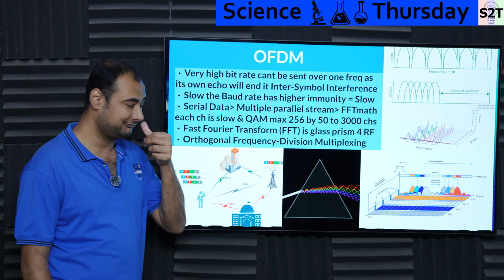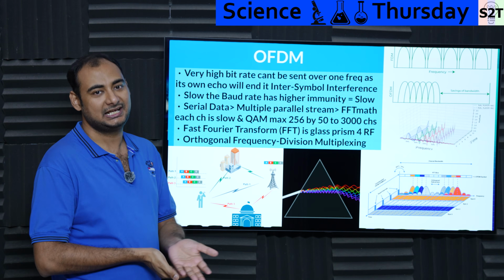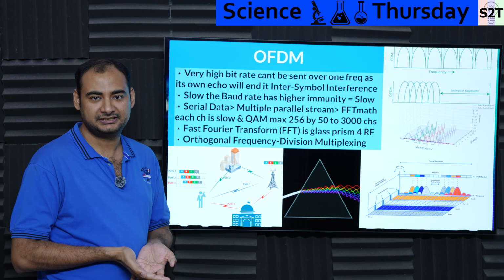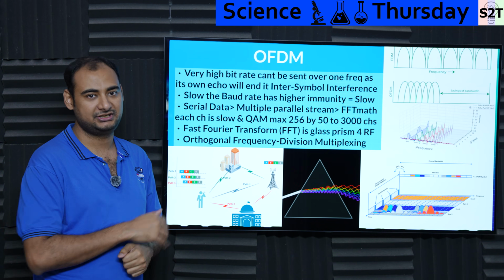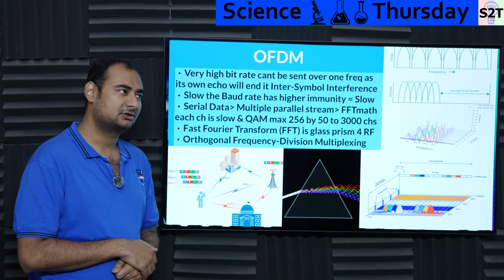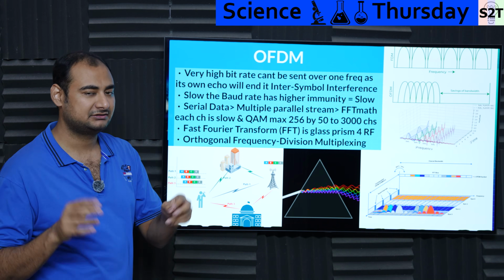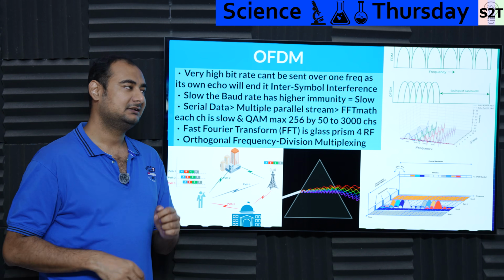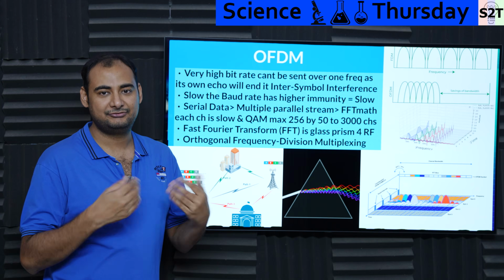Then we come to OFDM. Now OFDM is like a counter to reality, as in reality says, oh, you want to send so much frequency, we can't send it, right? Because again, signal degrades too quickly, noise overlaps everything, we have to reduce the symbol map. And then like, okay, what if I increase the frequency, increase the baud rate? Whenever you hear the word baud rate, it generally means the physical change, basically how quickly it's changing. Yes, it literally does this. So if you want to increase the baud rate, physics fights back.